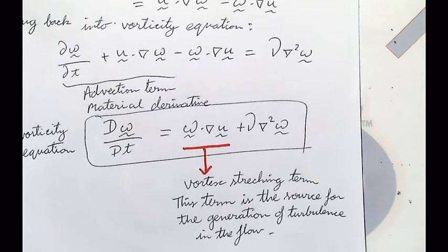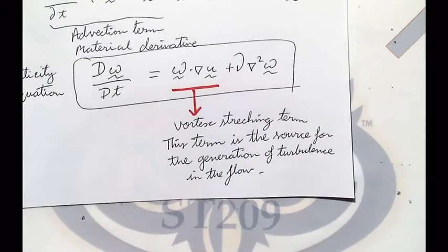It has been an ongoing topic of research for decades, 30, 40 years. So 2D simulations are good for low Reynolds numbers, but if you start going beyond Reynolds number 3,000, 4,000, 5,000, you're done. You're making an assumption that's not true physically.